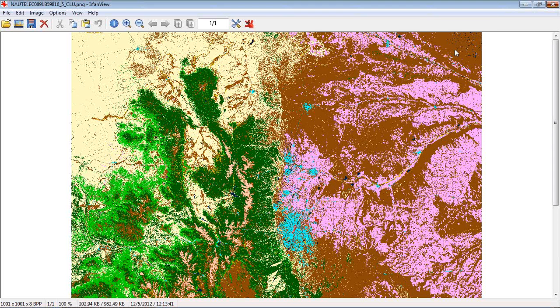Now I wanted to go through and explain what happens with television. Let's look at television too. So we'll turn to my coverage plots, and we'll bring up the 100-watt 4-bay antenna UHF ATSC and view that coverage plot. That shows what a 100-watt ATSC transmitter with a 4-bay antenna on the top of Lookout Mountain would cover. It covers the bulk of the population within the Denver metropolitan area, and does pretty well, actually, when you consider the distance here. That's 50 kilometers, and it's going almost 100 kilometers out to this point up here.